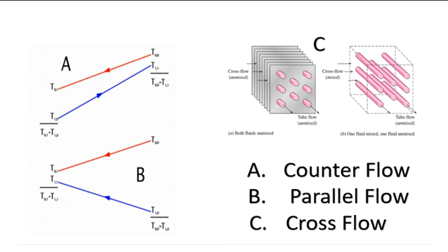In a cross-flow heat exchanger, the fluids travel roughly perpendicular to one another through the exchanger. This type of flow is suitable for handling low-density gas, which passes through the cross-flow, avoiding pressure loss. It can be used for liquid-liquid applications if one liquid has a considerably greater flow rate than the other.